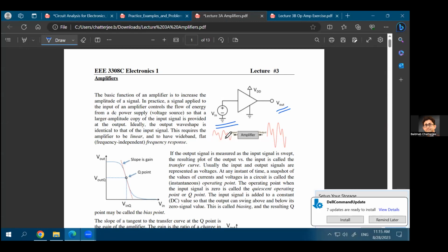The job of a transconductance amplifier, so just like there are voltages and currents, the ratio of voltage over current is called resistance, right? Or in a more generic term, this is called impedance. So what impedance means is that resistance is invariant of frequency. If you have a resistance R, which is V over I, that resistance is not varying with frequency. But there could be capacitive components, there could be inductive components which vary with frequency. So resistance is not a function of frequency, but capacitance and inductance are, or the impedance due to capacitances and inductances are a function of frequency.